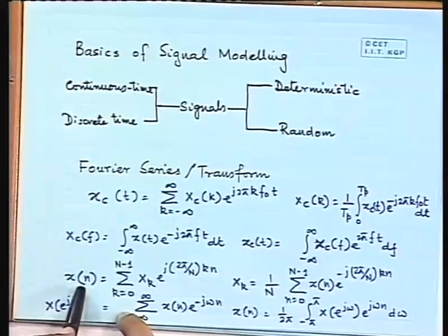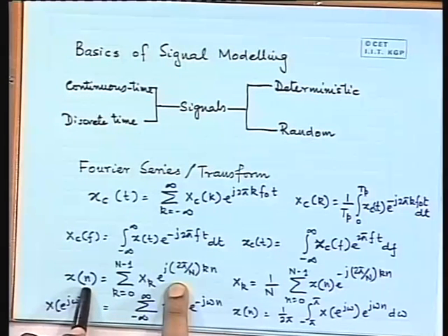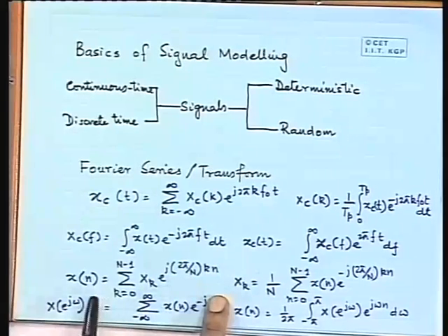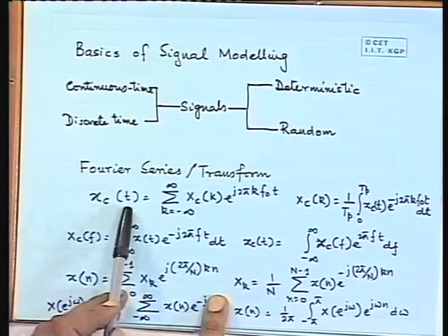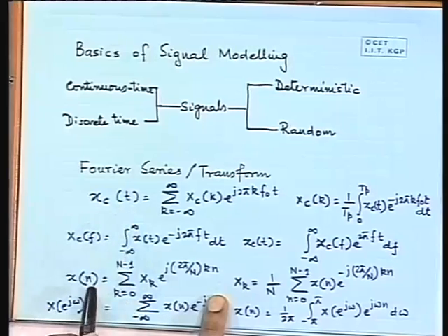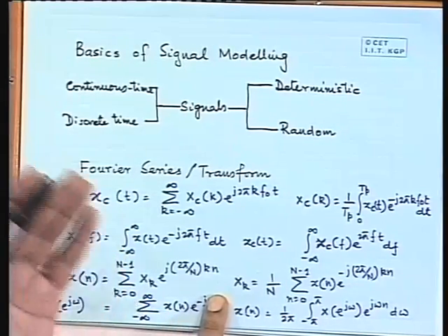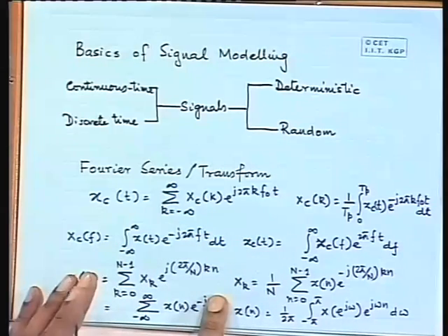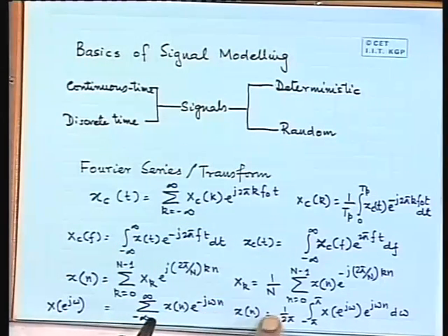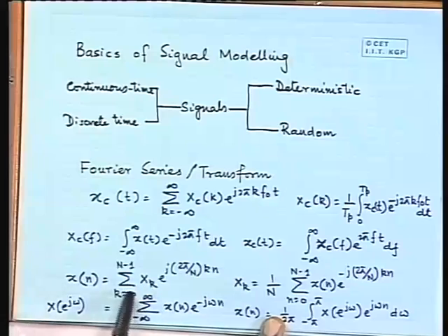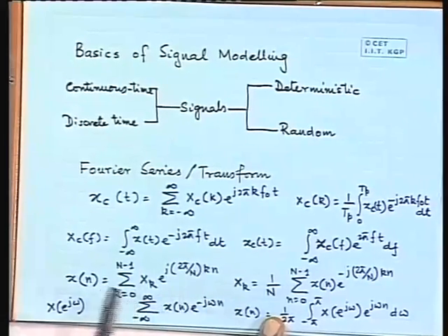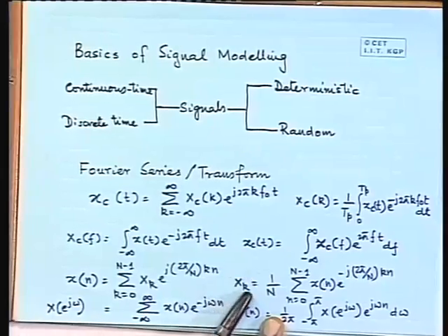Similarly, exactly similarly for discrete periodic signals, you can have a discrete Fourier series, where now I am only talking about n. Here I was talking about t. T is a continuous variable. Here n is a discrete variable, I mean numbers like -2, -1, 0, 7, only integers. Okay. And so these are the discrete Fourier components.